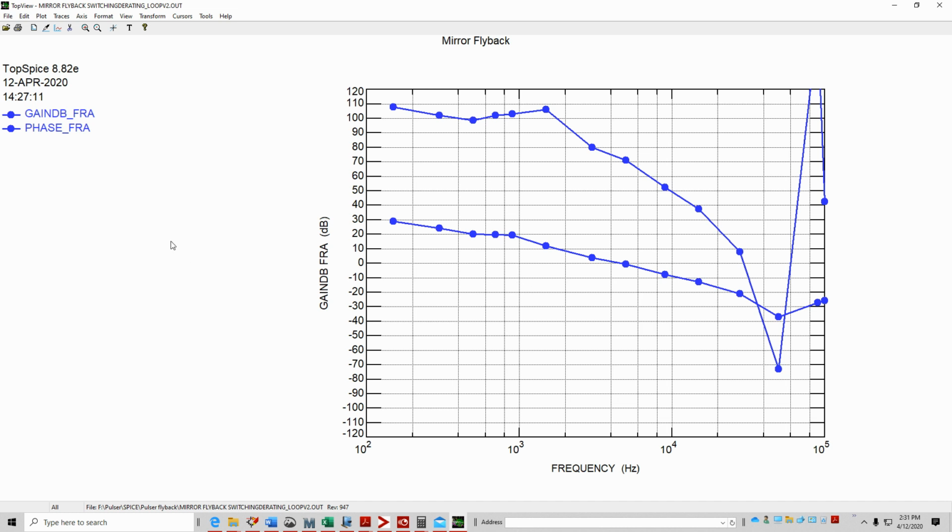Now a lot of times there might be a point, let's say like this point, or let's say there's another point. Typically you'll have noise up here in the high frequencies. Typically you can disregard that. What you want to look at is where they cross, basically the crossover frequency. That's what you want to know.